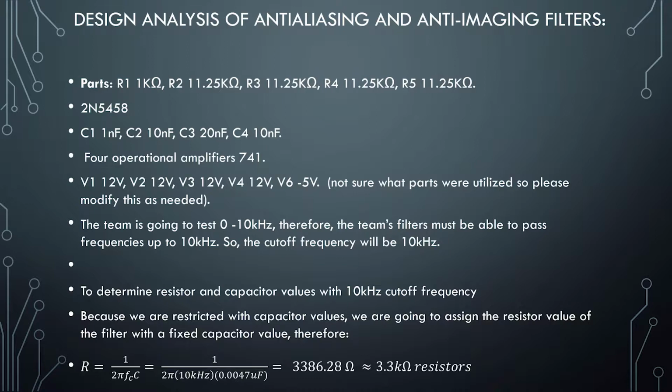We have a four op amp design, high order low pass filter that we played with, and we have tested with various resistor and capacitor values, as well as with various frequency values. But Multisim did not quite yield the results we would have expected. The highest frequency we used was 15 kHz, but again, results did not quite pan out.